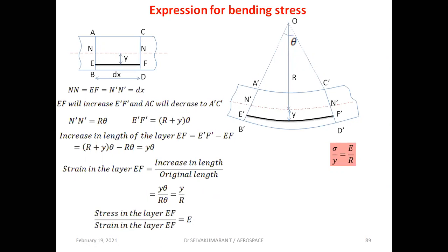How will you find stress? Stress by strain is equal to Young's modulus. Here strain is given. Let sigma be the stress in that small element. So stress by strain is equal to Young's modulus, and stress can be written as E into y by R.